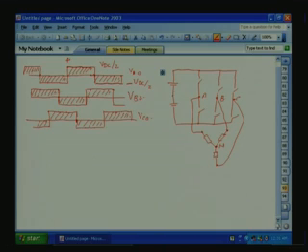And this is our fictitious O, Vdc by 2 and Vdc by 2. We are not actually using two DC link capacitors of Vdc by 2. For analysis, we are trying to measure the various pole voltages with respect to the fictitious center tap.